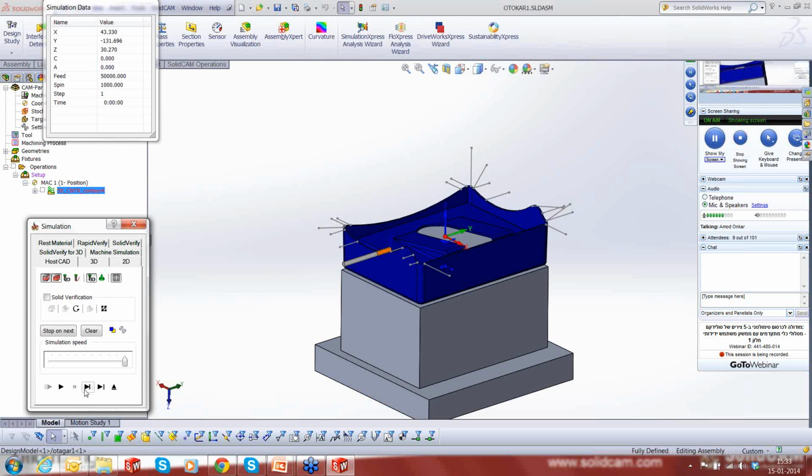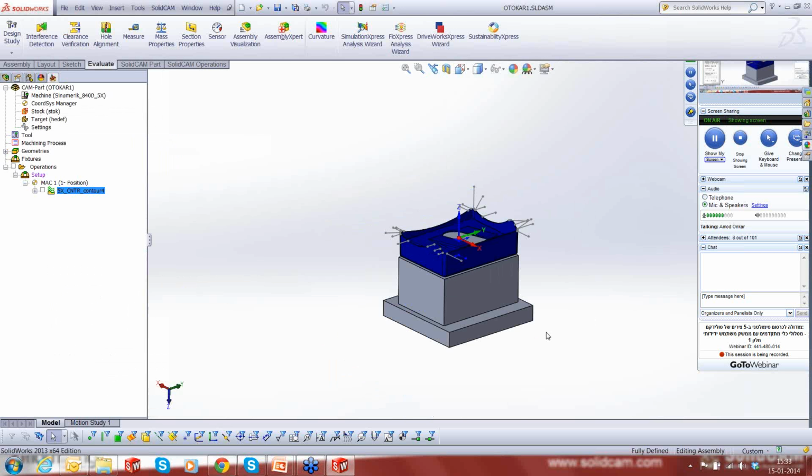Even in the aerospace industry, where there are a lot of aluminum sheet metal parts used, this technique of contouring is used in 5-axis to trim out the profile at the bottom, because these parts actually go and fit on some other parts, and the bottom profile is very, very important. It needs to be pretty much accurate so that it fits itself very nicely on the panels.